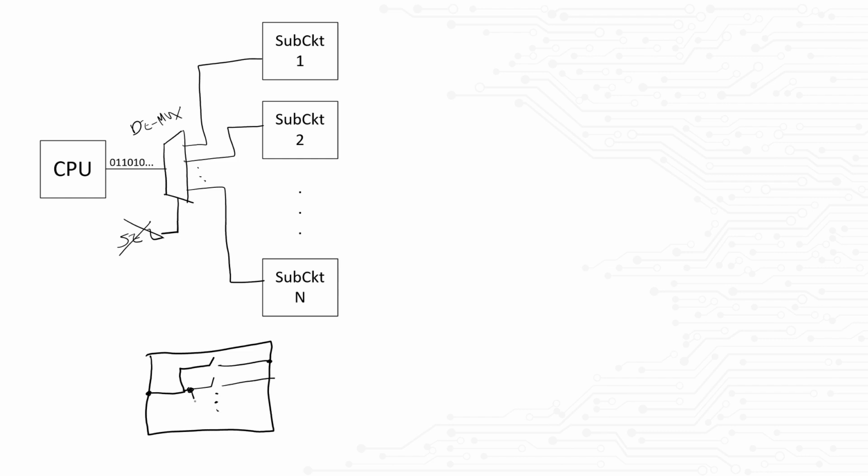If a mux-like structure is what we need, and the only information we possess is the incoming stream of bits from the processing unit, then it's possible to embed extra information within the string of bits to signal the mux where to direct the data. For example, when our mux structure detects a, let's say, 1010, then it knows to start routing the information to, let's say, subunit 1. When the sequence is 0101, it knows to stop sending bits to that subunit and is ready for a new sequence to go to other subunits. In this case, each subunit will have its own start and end sequence.